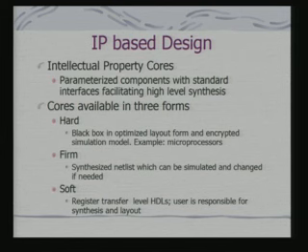In a hard core, the designer of a processor provides the design itself in a black box form, in an optimized layout. That means they provide it in a form which can actually go onto the silicon itself with the layout of the components being specified. They also provide an encrypted simulation model, so that the component can be used with other components in a simulation before you actually manufacture them.